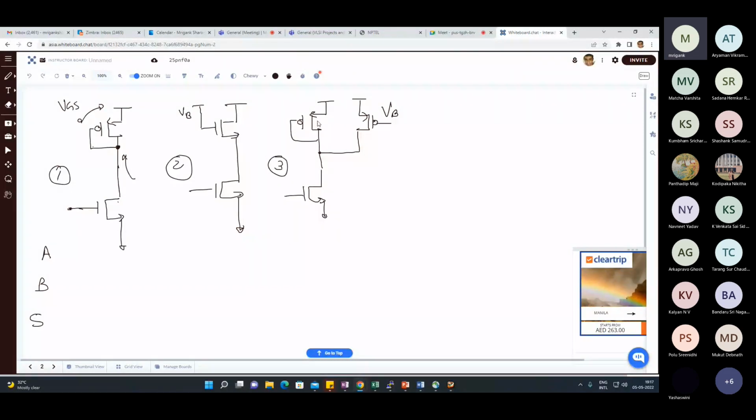And therefore, in order to find out the effective impedance contributed by this, I will look at the ID versus VGS curve. So if this is your ID versus VSG, for PMOS we can write ID versus VSG. I will look at this and figure out the slope, because ultimately here we are changing the VSG, and for that, how much change in ID will happen. If the VSG changes by a certain amount, delta, what is the change in ID? The inverse of this slope will give me the impedance looking upward, R up.